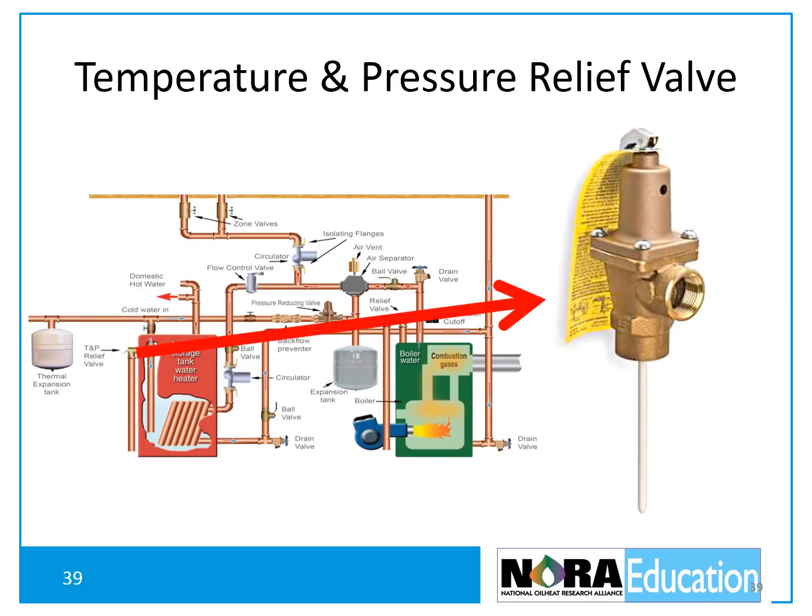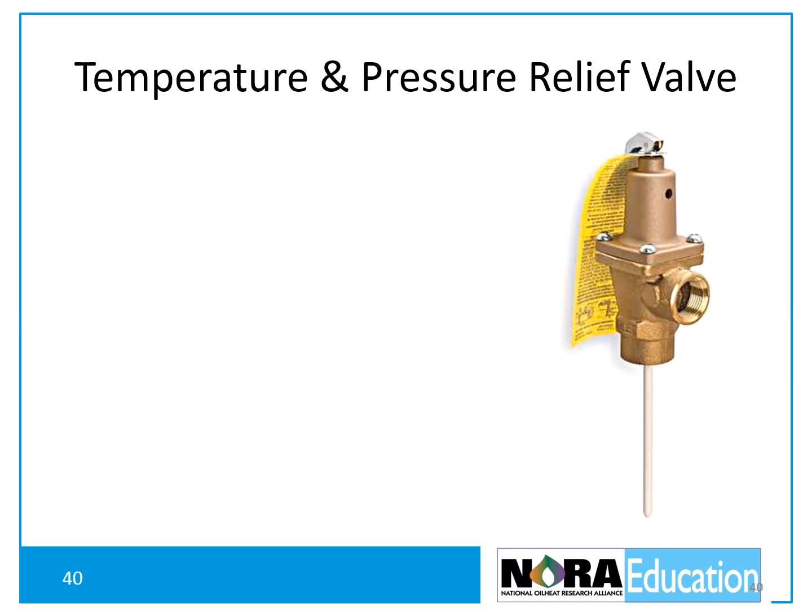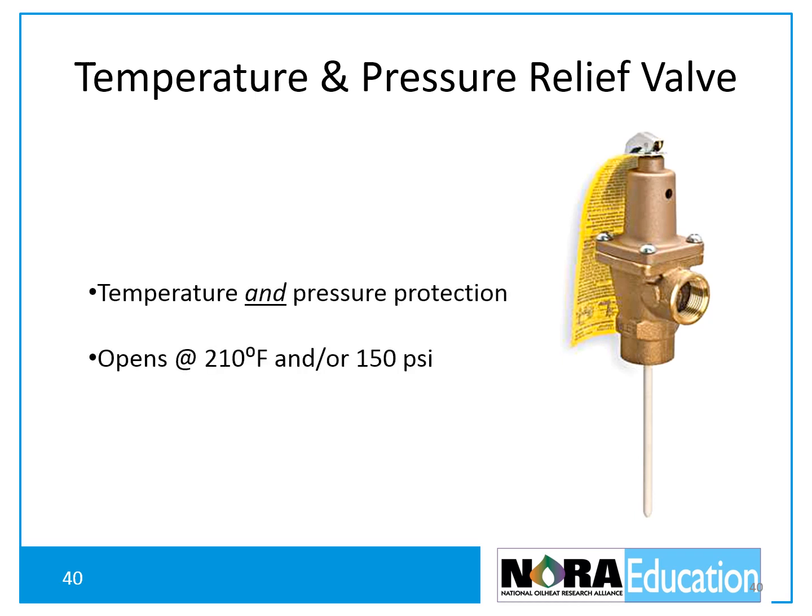Temperature and pressure relief valves. Temperature and pressure relief valves protect the system against excessive pressures and temperature. Typically, they open at 210 degrees Fahrenheit and/or 150 psi.